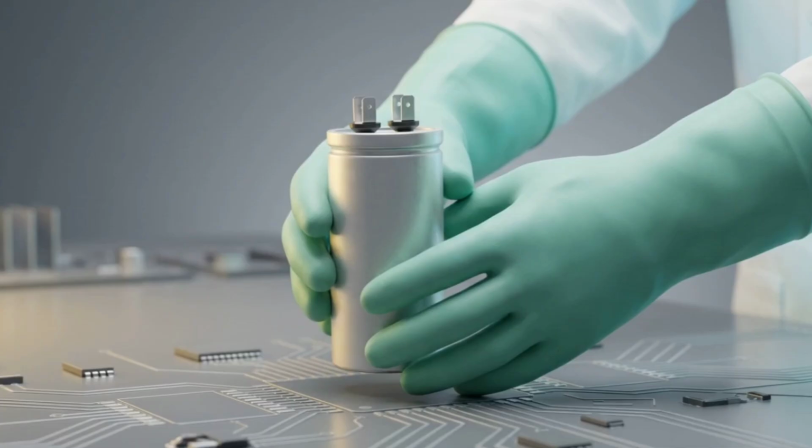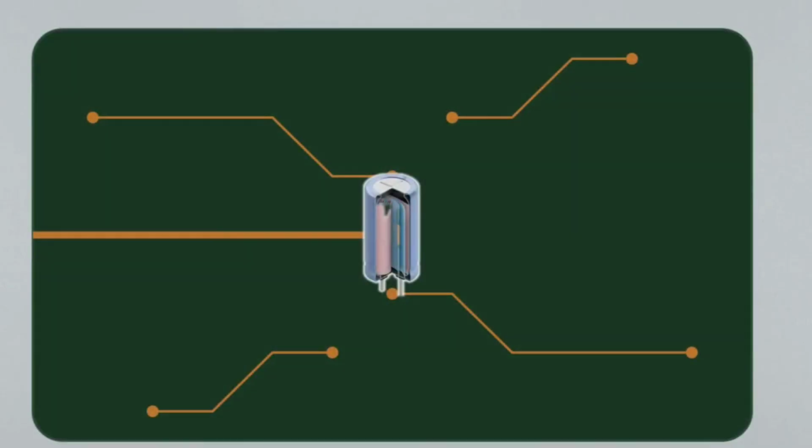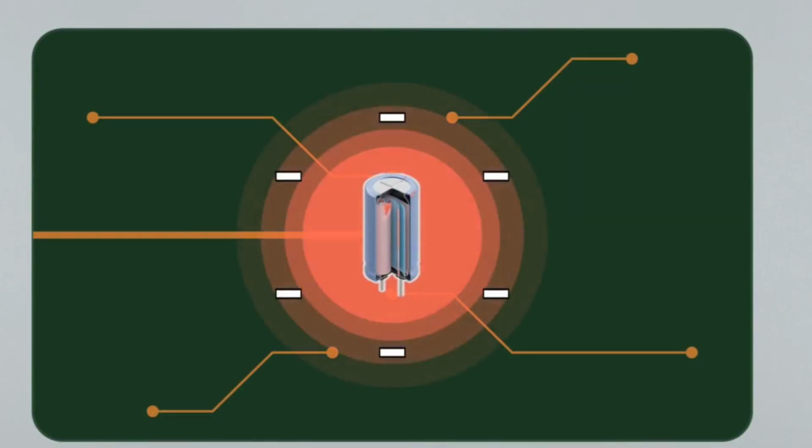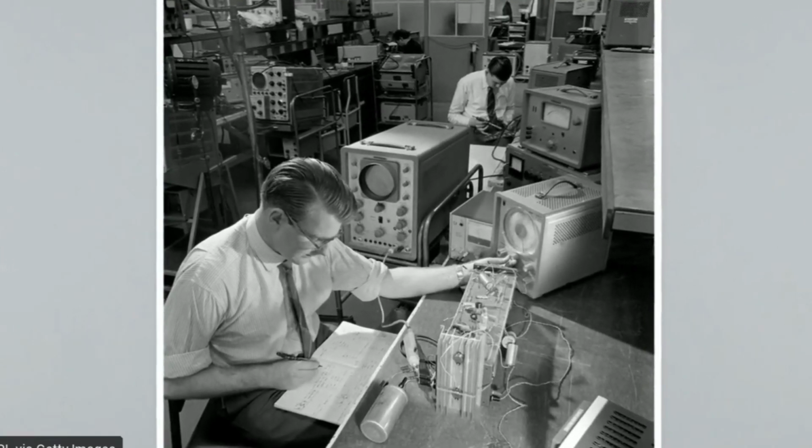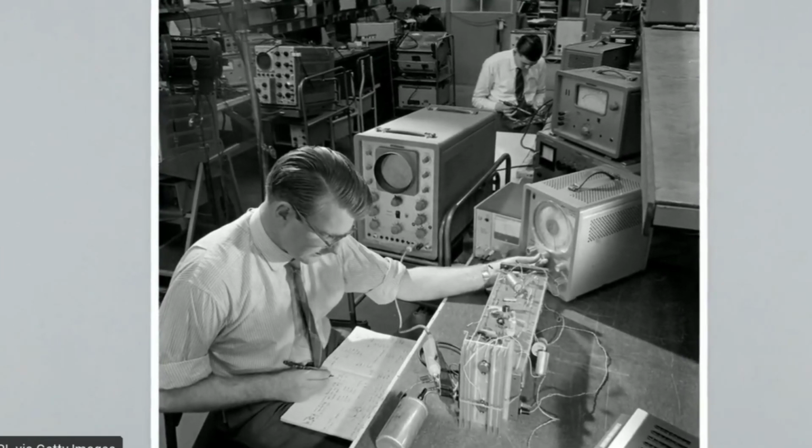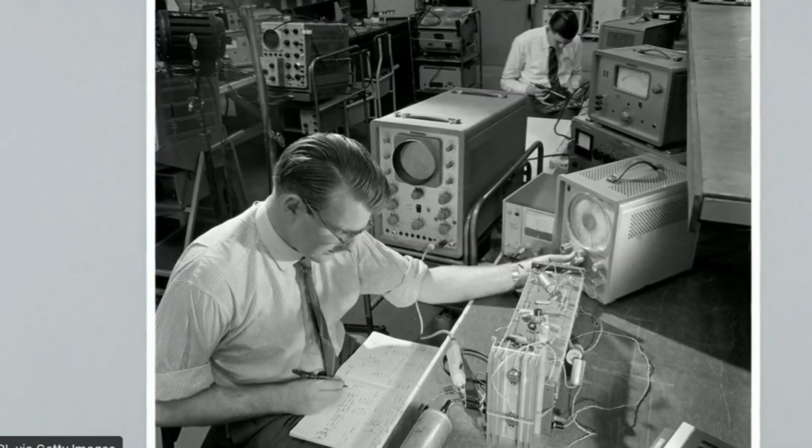Even when operated well within their limits and physically intact, capacitors require strict handling procedures. They retain lethal electrostatic charges long after the main power is severed. Verifying the decay of this residual charge is a non-negotiable laboratory diagnostic, practiced daily across the industry.